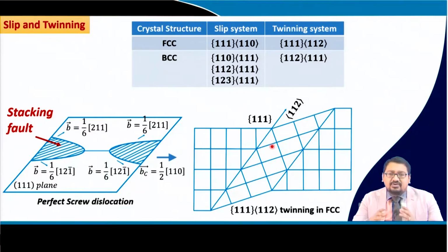in order to activate all the slip systems, cross slipping of screw dislocation and climb of edge dislocation leading to recovery is simultaneously needed in order for the deformation to sustain, and thus the deformation includes most of the time at least a little bit of recovery. So, we will talk about this later, but this is the whole thing and the most basic fundamental of deformation or plastic deformation.